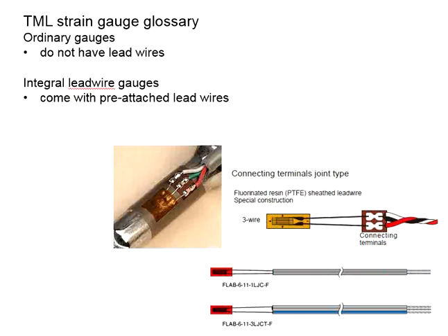You know that ultimately, the strain gauge will need to be installed onto the test specimen and then connected to the data logger. Now, if it comes without any lead wire, you will need to do some soldering and connect the wire to the strain gauge. This wire shall eventually be connected to the data logger.